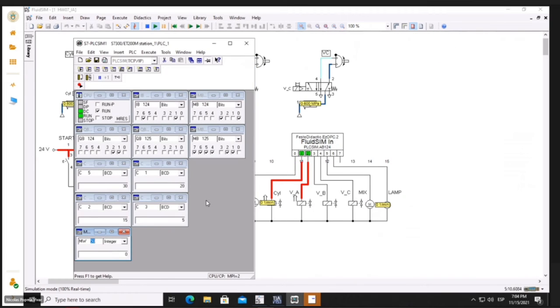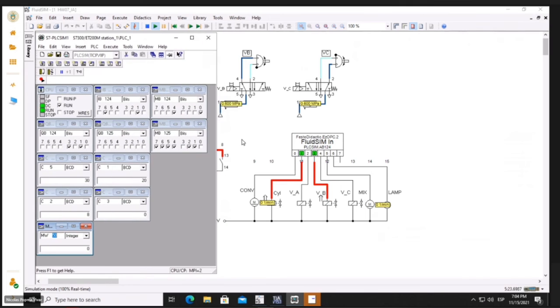And this will take a little bit longer because the times are longer. But as you can see, it automatically passes to the next from A to B and from B to C. And you can even see that movement in the top part of where the actuators are. As you can see, the little dot in the low part means that the painting is going down, like into the can, and if the ball is up, like in the case of BB, that means that that valve is closed, so no painting is passing through.